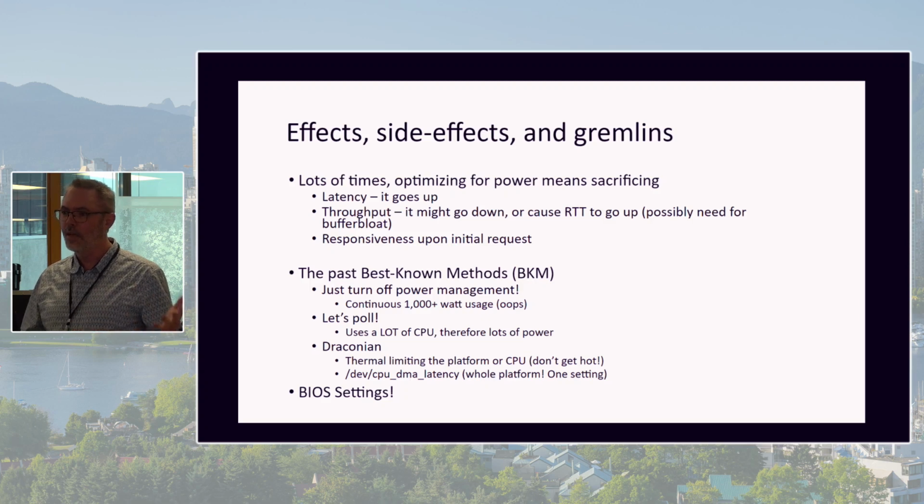And when we have really big systems with hundreds of CPU cores or threads available, it doesn't make sense anymore, to me at least, to tell my platform, just in case, let's burn a lot of extra power, maybe 10x the power of what you need to get your workload done, right? Because you might have a system that could idle for a few hours a day, or maybe it's idle for minutes at a time. Figuring out some kind of benefit to turning on the power management. The other thing that you get from turning on power management is your thermal envelope is very large, okay? So imagine that I have a heatsink on my processor that can dissipate 1,200 watts and fans that can handle it.